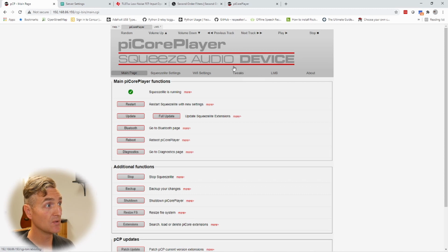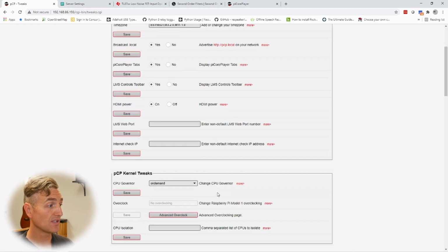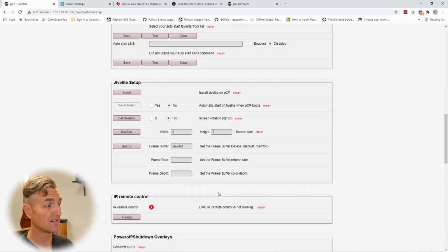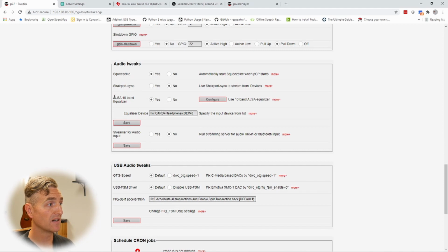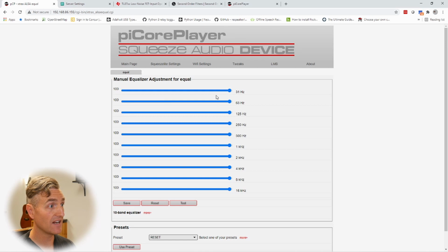So what I want to do with this Raspberry Pi, all that can be a deeper explanation later. Mostly, I want to use the DSP that is available in my audio port for the Raspberry Pi. So the DSP is an equalizer that I can now configure on the fly in the Raspberry Pi, and it can essentially do all those fancy equalization curves that I was building with resistors and capacitors and op amps, all inside of the silicon on the Raspberry Pi. So I need to do some changes to my board.